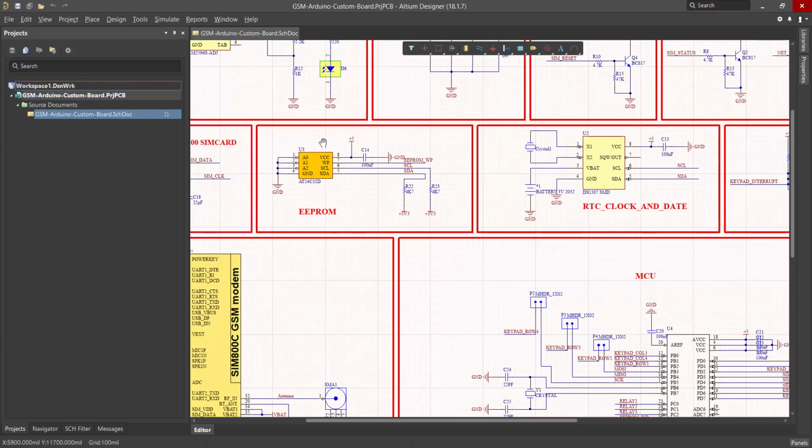As I2C is an open collector bus, I will teach you what open collector is in next sessions. So we need to pull up these lines with resistors. The value of these resistors can be in the range of 2 kilo ohm to 10 kilo ohm, depending on our power supply. We use 4.7 kilo ohm resistors in here.